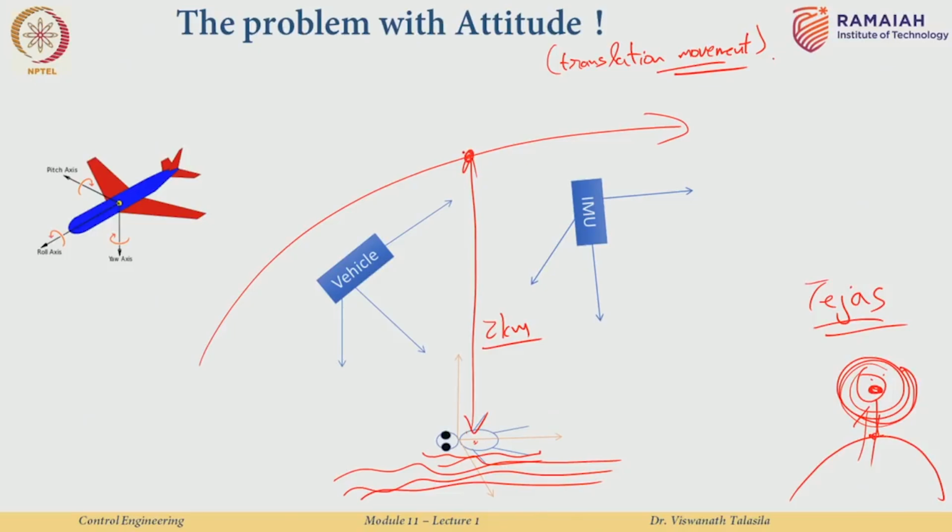There is a further problem. You have the aircraft shown over here, okay. Now of course the aircraft flight control system needs to be able to compute its own position. So it places these gyroscopes, accelerometers and all these things in the aircraft. Now where does it place it? Let us say for example it has placed it, let us use a different color, white, over here, okay. So this box, it is actually a very small box, is placed over here, and this box is going to do the measurements of angular rotations as well as accelerations, the IMU.